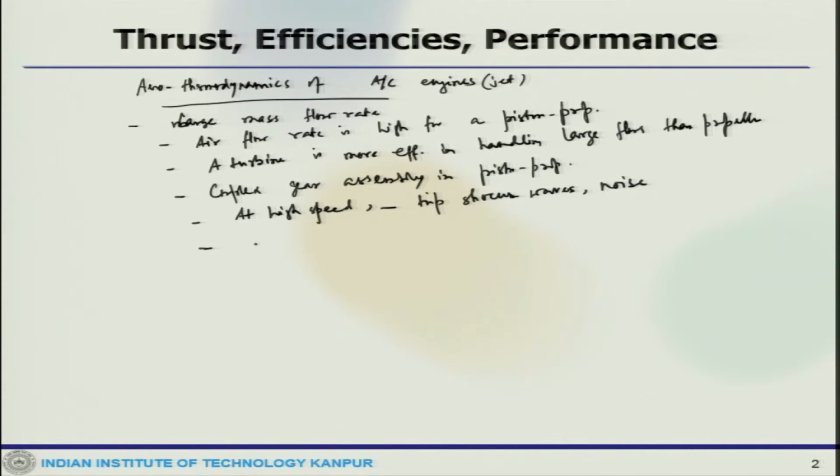So, when the gas flows through the turbine, it turns the turbine, and the rotating motion of the turbine can be used to generate power, as the gases expand across the turbine. Now, to have gas flow across the turbine, there must be a pressure drop, delta P. Hence, a pressure ratio across the engine must be provided.